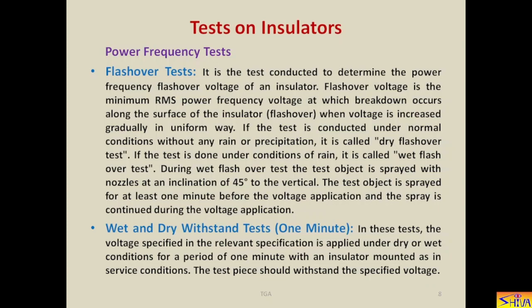Now, the value of the withstand voltage as well as flashover voltage depends on the rating of the insulator, and for a particular rating of the insulator like 11 kV, 22 kV, 33 kV, or string of 132 kV, what should be the minimum flashover voltage, and what should be the wet and dry withstand voltage, they are given in relevant references.